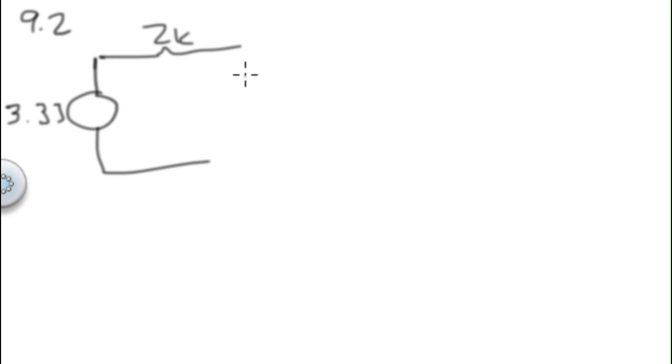So the Thevenin circuit would be 2/3 of 5, or 5 times 2 divided by 3, or 3.33. So basically, we're invited to do this. This is 3.33. And then we go over here, and we've got a 2K up here. Now we've got a capacitor. We've got to find the impedance of it. So Thevenize when you can, and that's what we're going to do. So all I'm going to do is find that I right there.